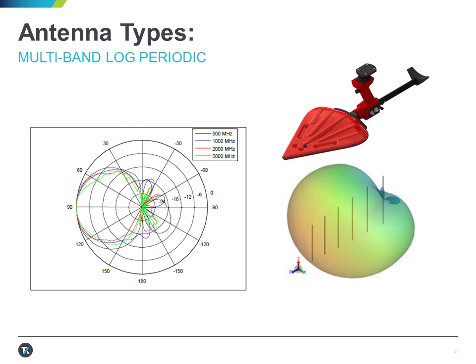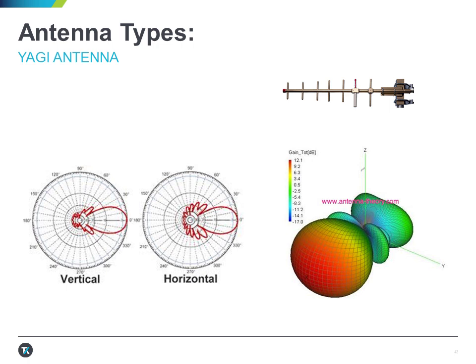Note that as you get closer and closer to the target emitter, these types of antennas lose their efficiency, and it's more accurate and more efficient to use an antenna with less gain or less directivity. By comparison, a Yagi antenna is much more directive. It has a greater front to back ratio and a much narrower beam width. The trade-off is a much narrower frequency range.